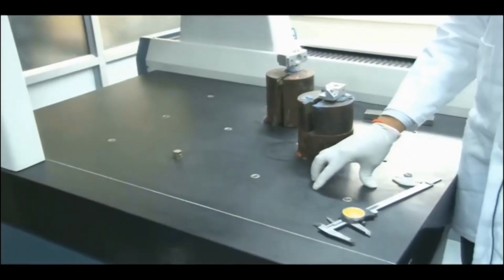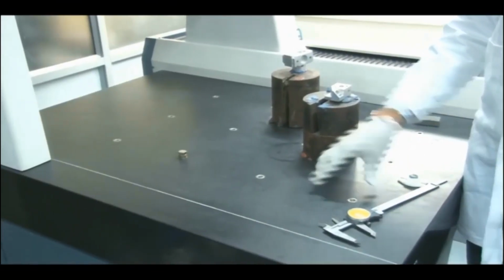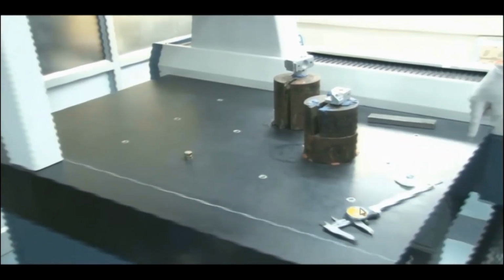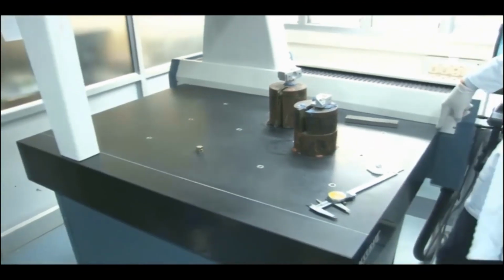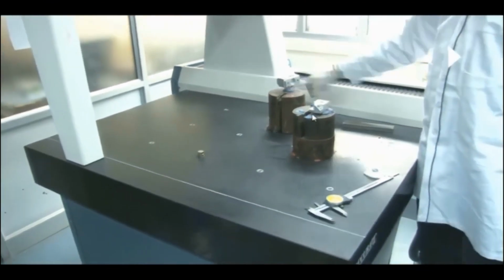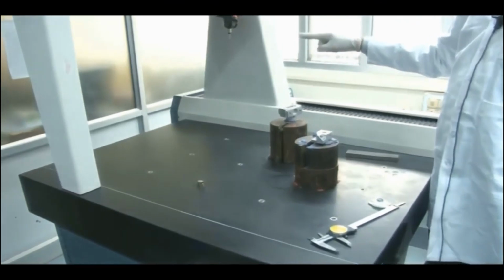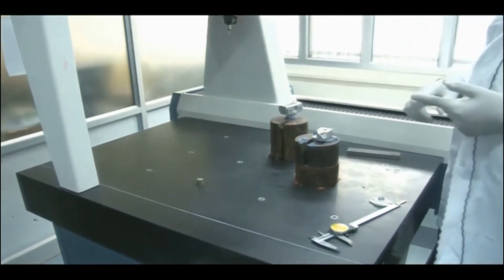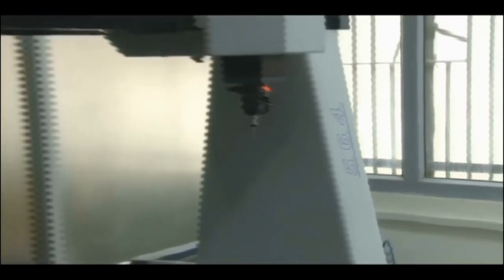Other components: we have this software, and we have this granite surface plate, or surface table, here. This is a 0 grade surface plate. As I said, the accuracy is quite high and the thermal expansion is 0. The size of the machine is 500 in this direction, 600 from here to here, and the height is 400. That is why it is known as 564. So this is the Spectra 564.